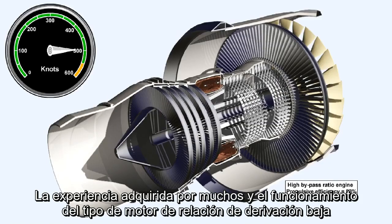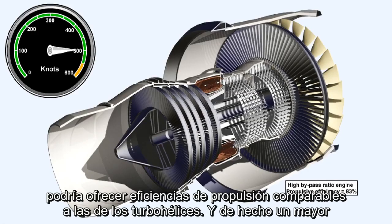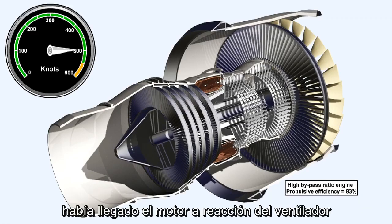The experience which was gained by manufacturing and operating the low bypass ratio type of engine proved that engines which dealt with a larger comparative air mass flow and lower jet velocities could deliver propulsive efficiencies comparable to those of turboprops, and, indeed, a higher propulsive efficiency than turbojets operating at normal cruising speeds. The advent of the fan jet engine had arrived.